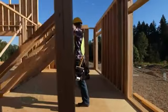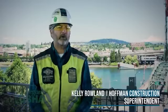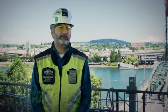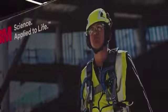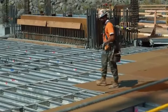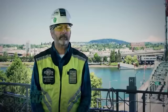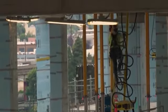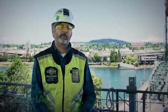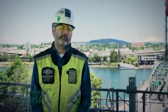The most important one would be just taking safety as a cultural change, and it's part of your work. It's not a hassle. Safety all the way down to wearing the right safety glasses, wearing the right boots, no tennis shoes, no short pants, no sleeveless shirts, that kind of thing, and just really embrace the safety culture. Well, not everybody is going to want to do it, but you have to set the tone on your project. If you're going to work here on my job, then you will be safe. You will follow our safety protocols. And if you don't want to do that, we don't want you working with us.